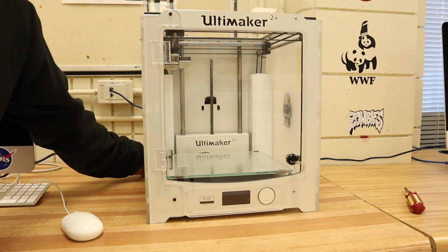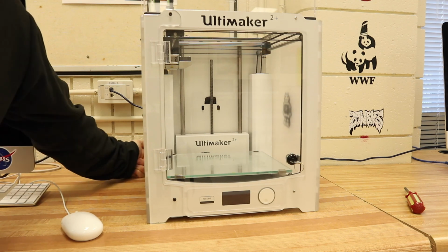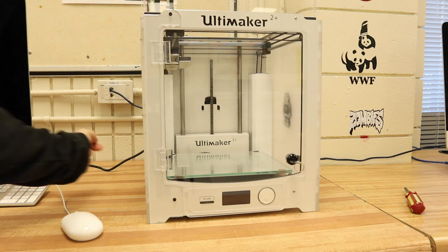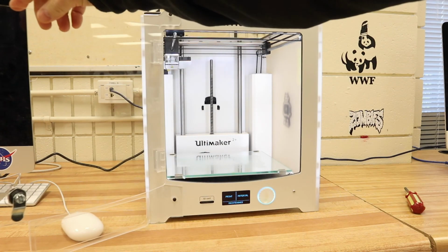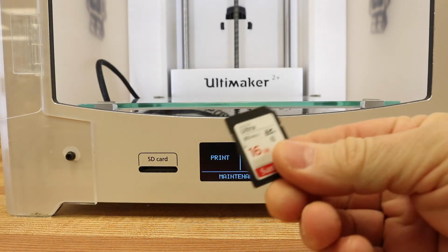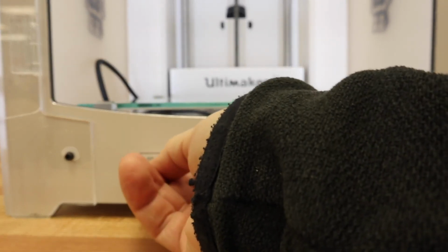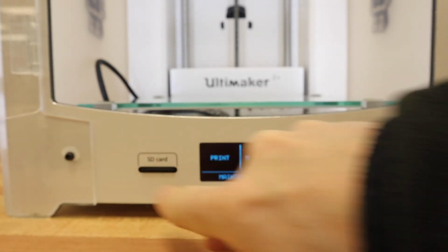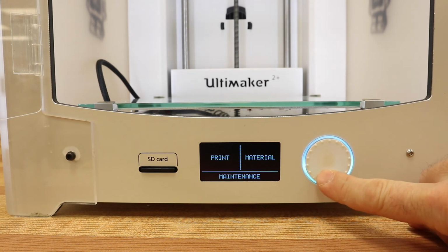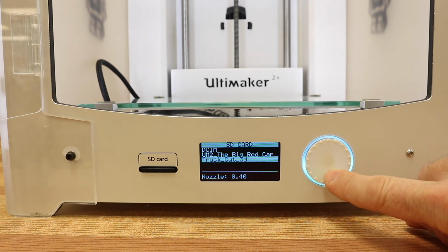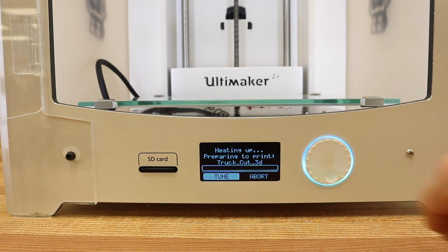So when you get to the 3D printer at the back, you'll turn the printer on, and then open up the cabinet, insert your SD card. With the circular button, scroll it until it gives you the option to print. Press the button, and then scroll again to find your file. Press again, and it will print out your cookie cutter.